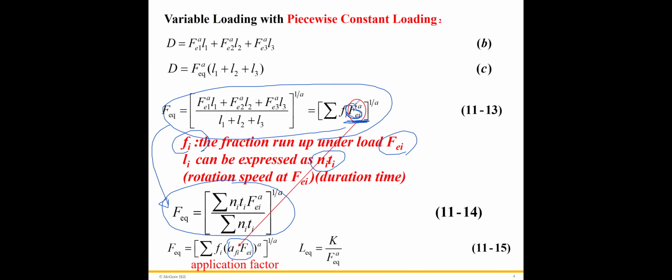So we get this equivalent load for the practical scenario. You have to apply the safety factor depending on different applications, right? This AFi represents the application factor, or the safety factor.